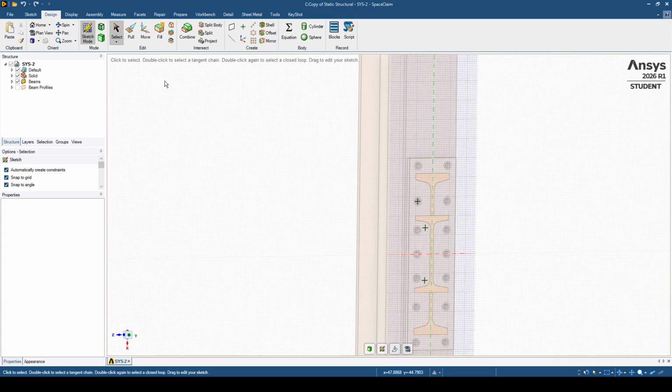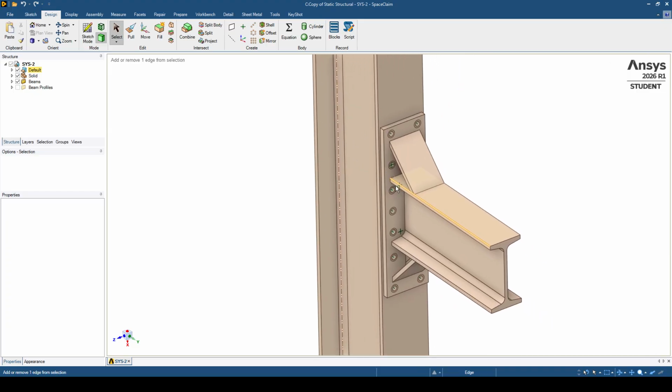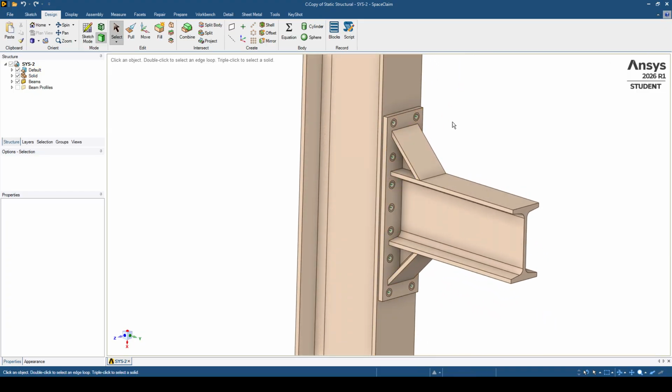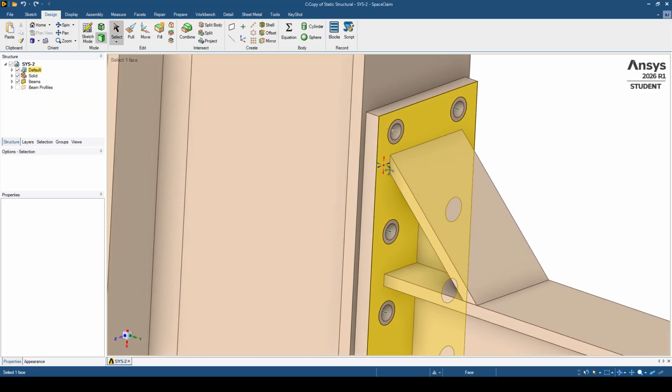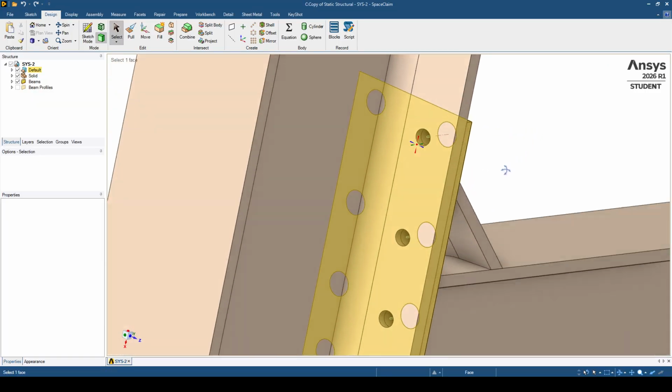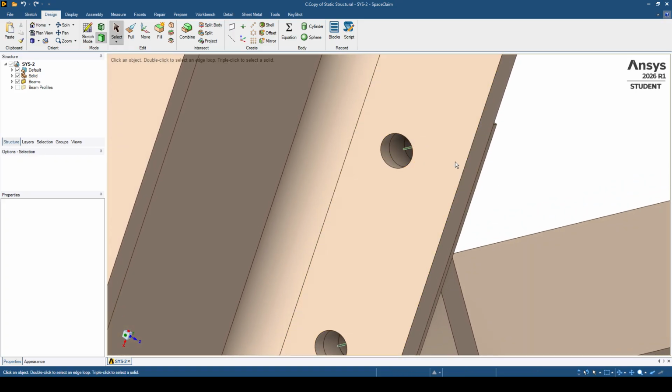I already prepared that for you, so you can find this file in the description as I told you before. After you prepare these surfaces, you have to model the beams: draw points at the center of each hole that we have here, and extrude them until the end of our thread, which in my situation is until this location. So at the end we have this beam.